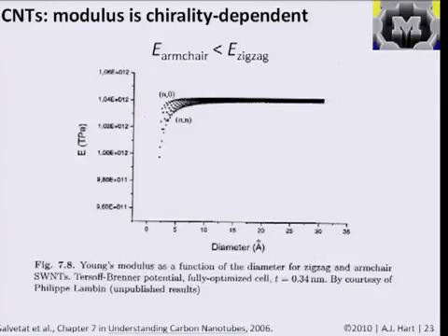So here is a plot of the effective Young's modulus in terapascals. You could say this is about 1. This is 1.04, but we can call it 1. And although these effects are small, we're down by a few percent here, we can see generally as the diameter goes down, we see a decrease in the Young's modulus. And mind us here that the diameter of 10 angstroms here is 1 nanometer. So we're talking about really small nanotubes.